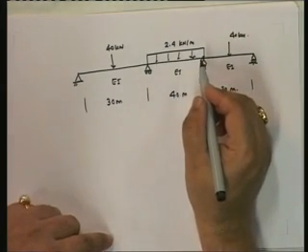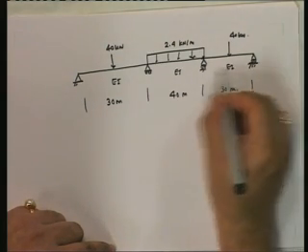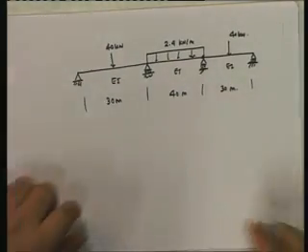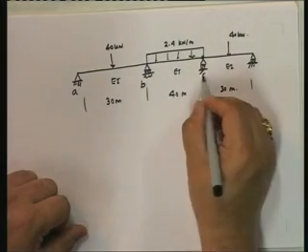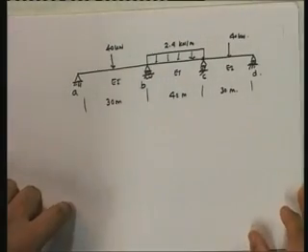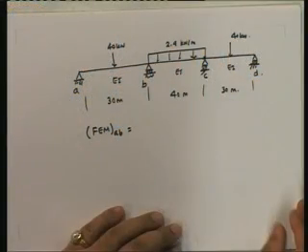For this one we need to find out the end moments and then the bending moment. Once you have the end moments, the bending moment diagrams are obvious. So A, B, C, D. First and foremost, I'm going through the steps algorithmically, applying the moment distribution method to a beam problem. Today we are only going to be looking at beam problems, and from the next time onwards we'll see how to consider a frame. So let's look at a beam.